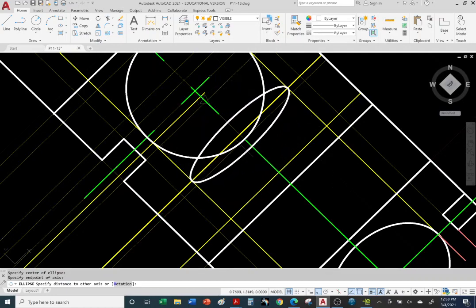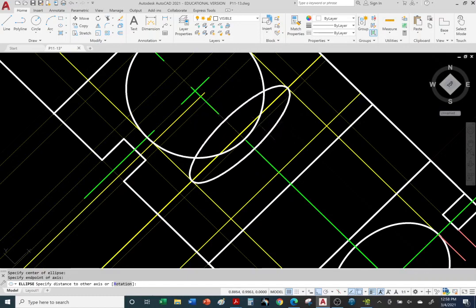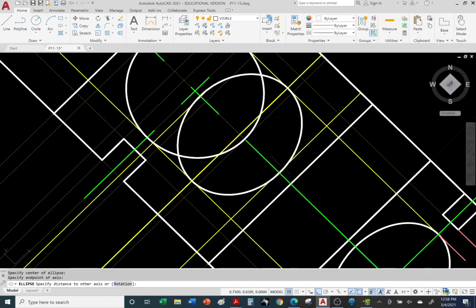There it is. You can see it, right? I'm not shaking. It's Object Snap trying to snap. It's not my hand that's causing all this shaking. Okay, and we can either go to this point here to define our other diameter, or we can go to this point here, right there, where the green center line and the thick construction line intersect, and click. There's our exit. Ta-da! So some of you are saying, hey teacher, it's only supposed to be part white visible object line, and the other portion is supposed to be a red hidden line.